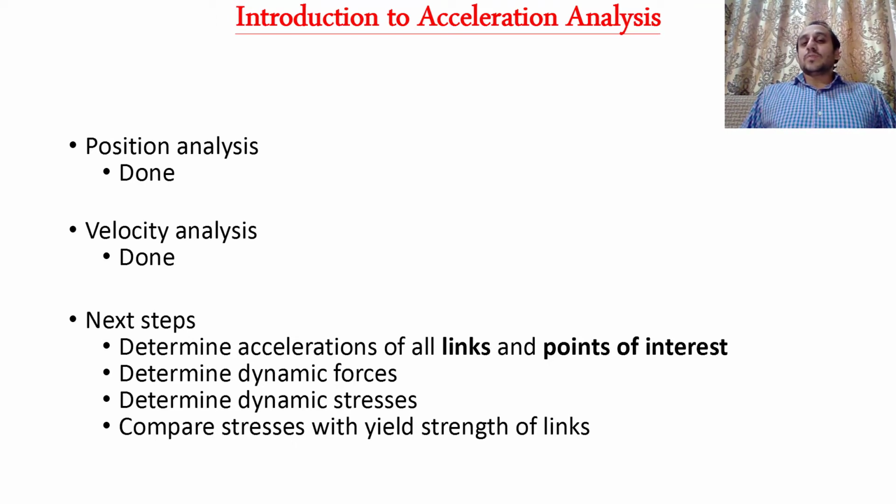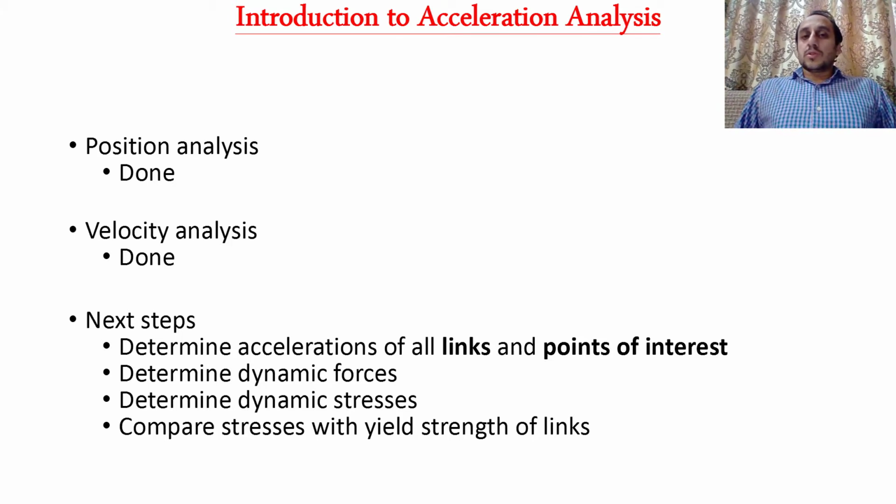This is so that we can find out whether, during the course of the motion, the stresses are going beyond the yield strength, because if this happens the links will be deformed permanently and the mechanism will not be able to perform the role which it is supposed to perform.